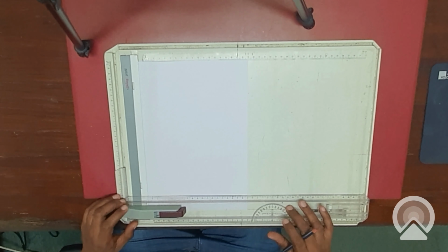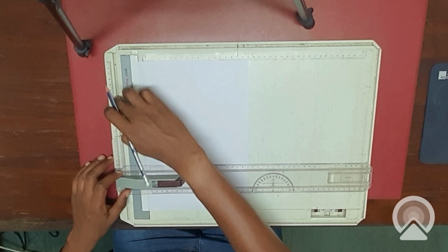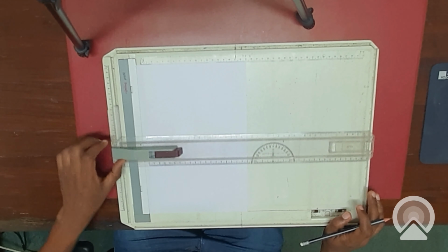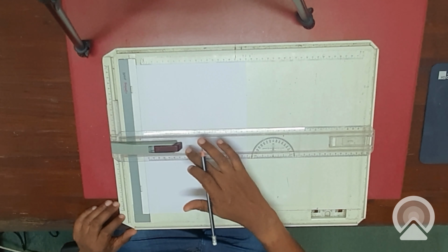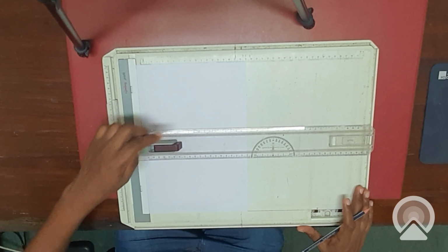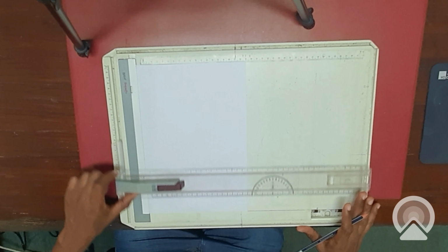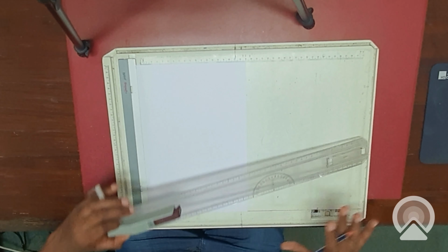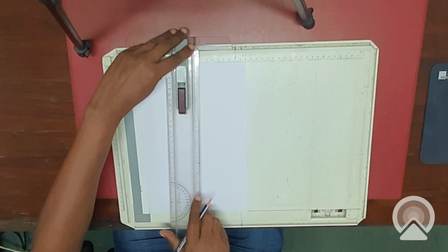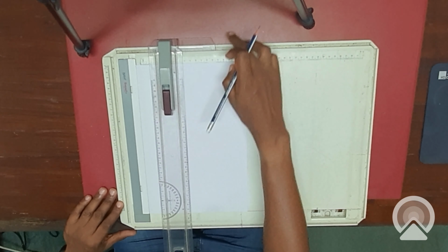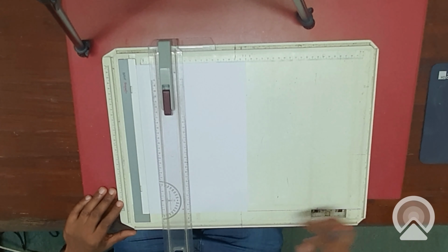So we are using the T ruler to draw horizontal lines, but the important thing to note is to make sure that your T ruler is always on the groove, this way. And you have a locker here. If you lock it, the T ruler doesn't move, but if you unlock it, you can move your T ruler easily. So you use this to draw a horizontal line. And if you want to use the T ruler to draw vertical lines, you can rotate this way, and then make sure they are within the grooves, or you can put it on the lower groove this way.